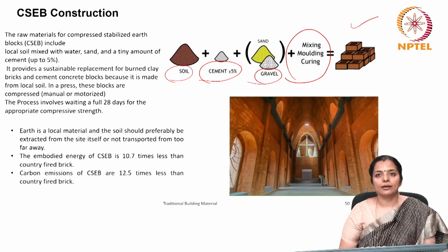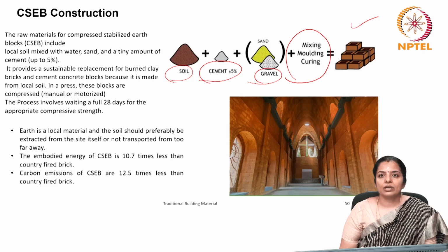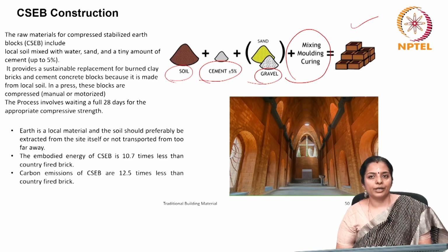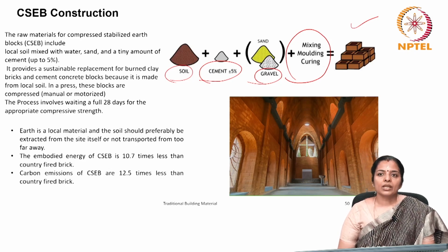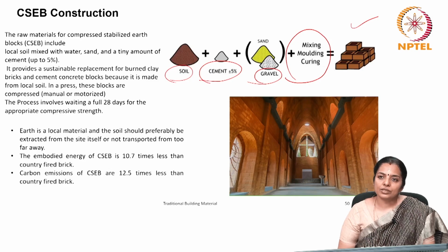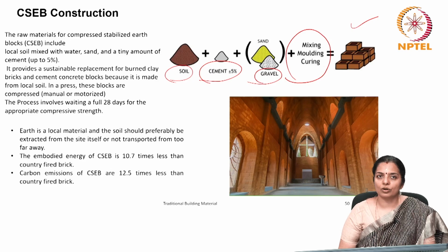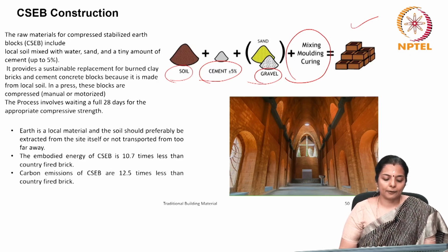So not every soil is suitable for making these CSEB in particular, but with some knowledge and experience, most of the soils can be used for producing CSEB. Again, topsoil must not be used, and a simple analysis of the soil will be good for us to be very confident in going ahead and doing it. For very sandy soils, we can use cement as a stabilizer, and we can have lime stabilization for clay soils. These basics can be followed to make it a very enduring material.